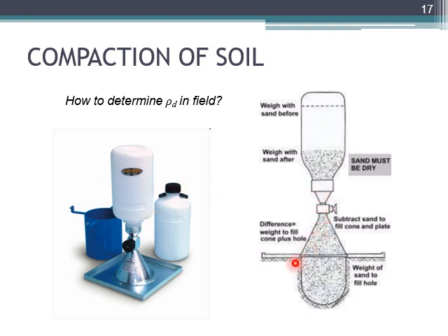We put that cone over the hole that we have created, and we have the standard sand in the container. We weigh the sand before the test.